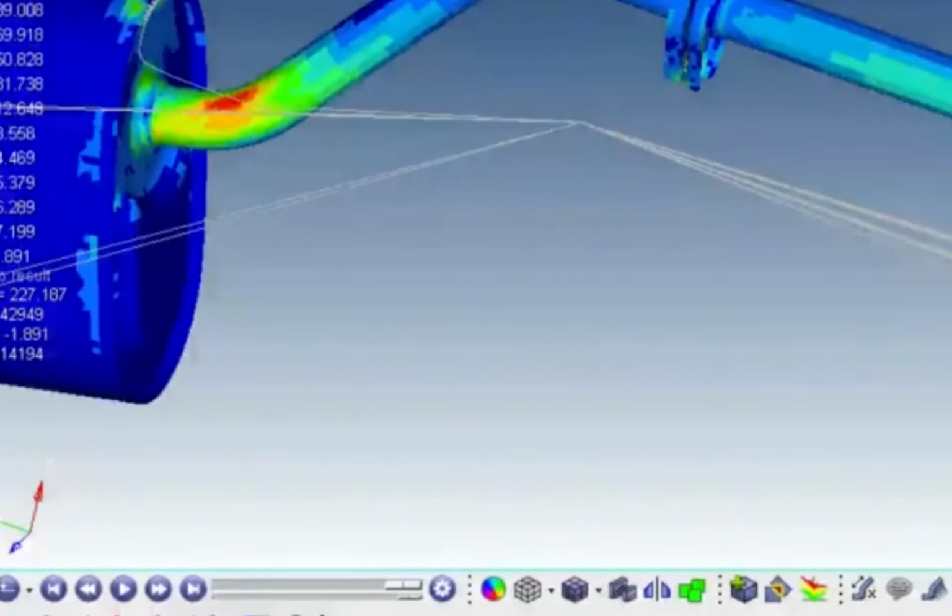So it's 5 times the 45 plus a very tiny mean added on to the top. So that's quite a nice statistic that you can estimate from that. The other thing that we can do is we can take all those stresses that are linear results estimated from the linear analysis, and we can convert them into elastic plastic strains. So we can calculate the RMS strain,